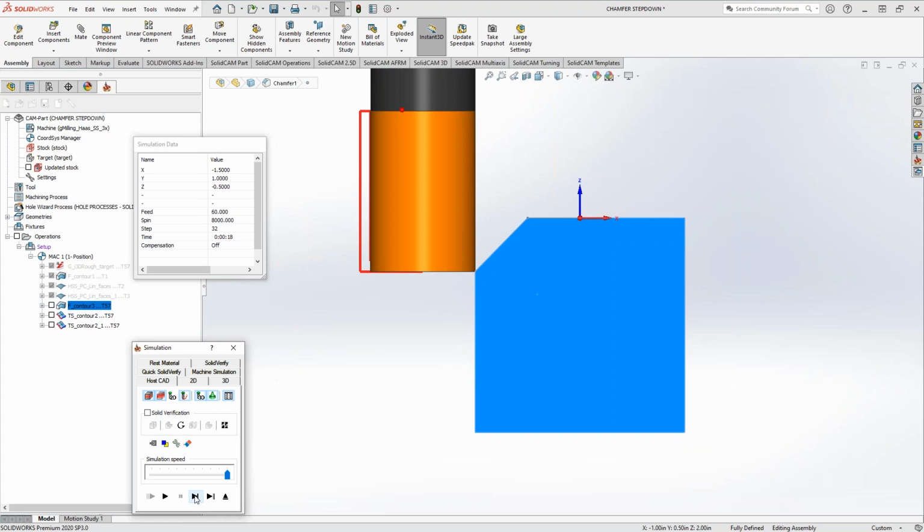So this is another way if you have a very simple geometry like this, basically just a wall draft angle to your profile, then you can get this done as well. And if you didn't have HSS, this would be the way I would do this one, especially if it's just that simple 45-degree angle. If it has any kind of weird profile to it, then that's a translated surface. But if it's literally just this one line, then I wouldn't bother sketching. I wouldn't bother even looking at translated surface. I would come right here.